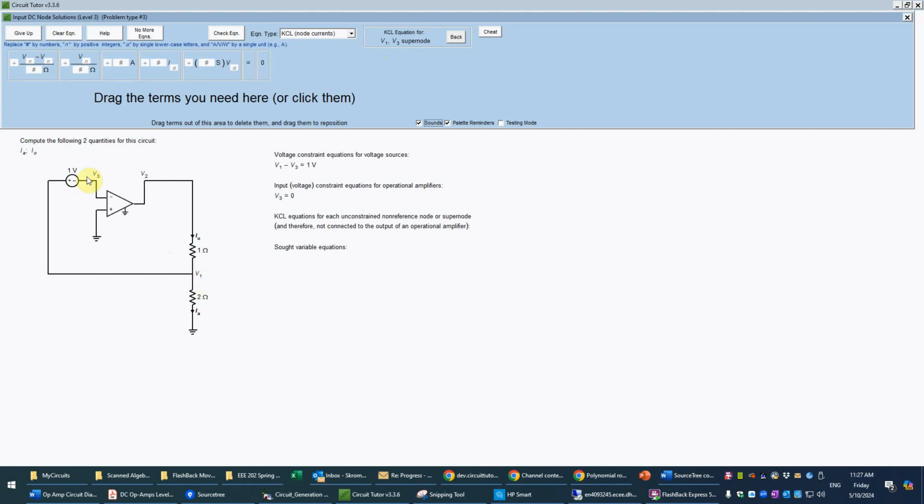Okay, so the current here is 0, so we don't need to worry about any currents involving node 3. And node 1 has 2 currents, namely leaving it through the 2 ohm and leaving it through the 1 ohm, or entering, whichever. So the 1 ohm current is going to be a single node voltage since the other side is connected to ground. Here we have 2 different node voltages, so we'll need a term like this, and the sum of those equals 0.